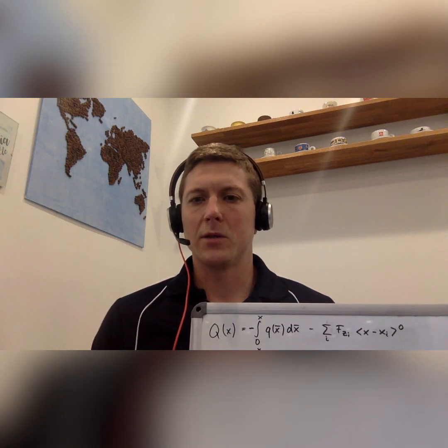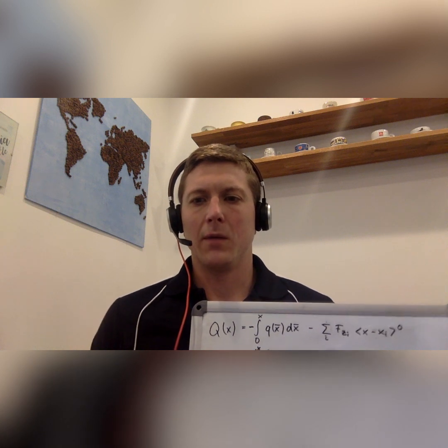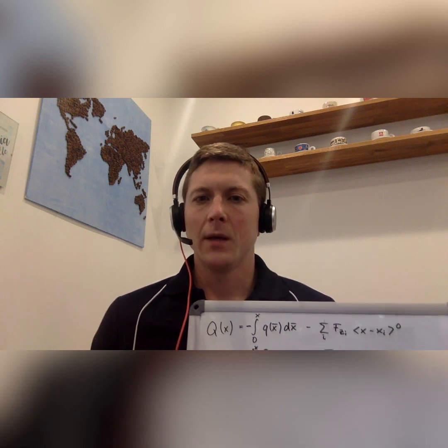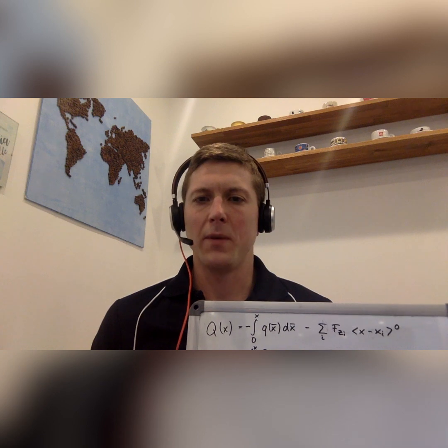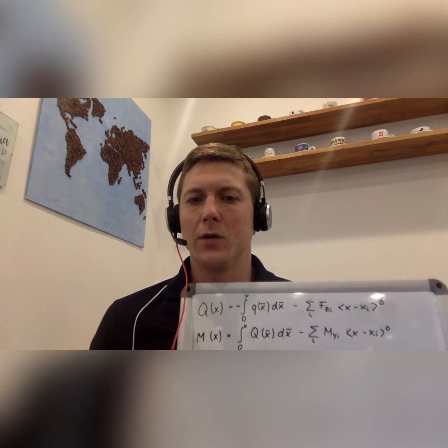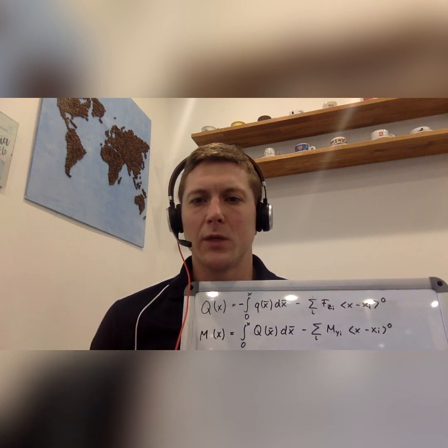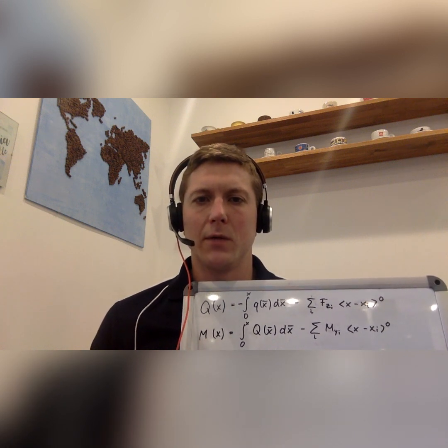And you could say this is just a jump function. So if the Macaulay expression is negative, then no consideration, and otherwise it jumps downwards with the amount of F_c at this position xi. Yeah, and the next step to get from the shear force to the bending moment is simply a further integration, so an integration over the shear force itself and minus all discrete moments which are acting with respect to the y-axis at their position. So same way as to integrate the discrete forces for the shear force, here you have to subtract all discrete moments acting at their specific positions.